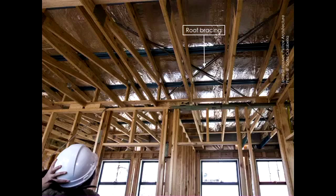And the interesting thing, when you go to visit a construction site, being able to see things in 3D, you realize that bracing is not strictly related to a wall. It's also related to lateral stability. So it's about this wall here, but also the wall in the orthogonal direction. And also it's about the flooring system that's on top of my head. So those joists, those trusses actually, they need to be braced in that direction.